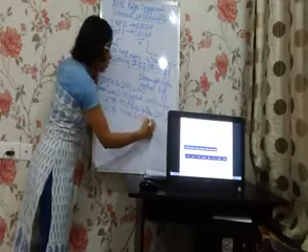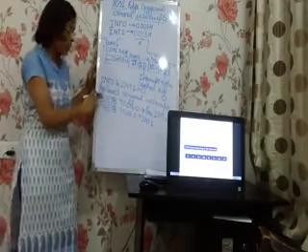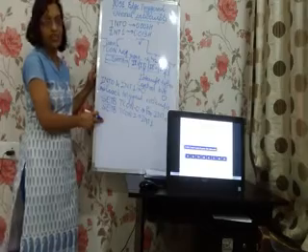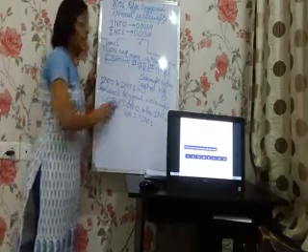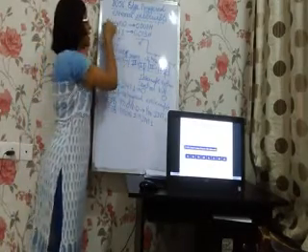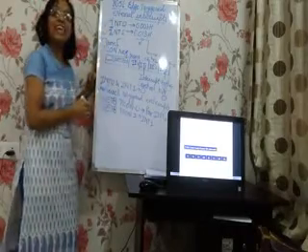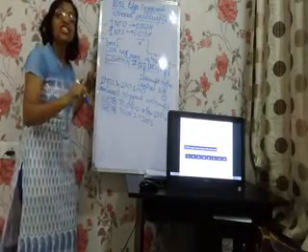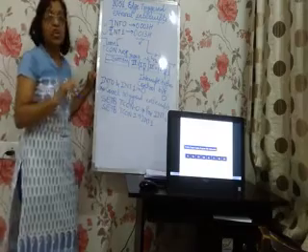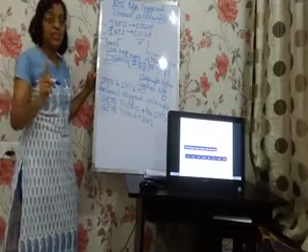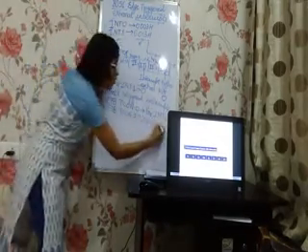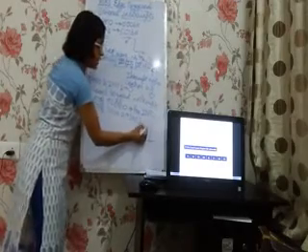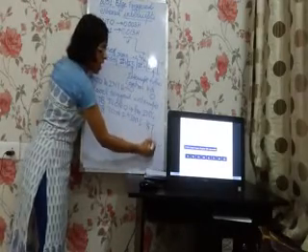If we set one of these two or both of them to 1, it means INT0 and INT1 are defined as edge triggered interrupts. So the microcontroller will be interrupted when a falling edge, a high to low transition, is detected.